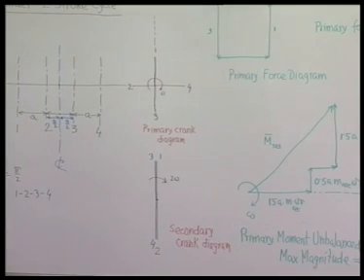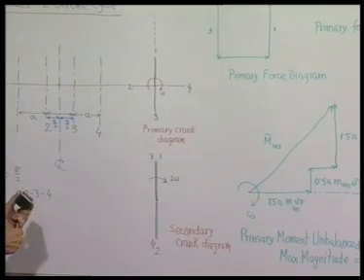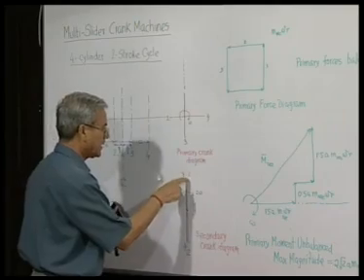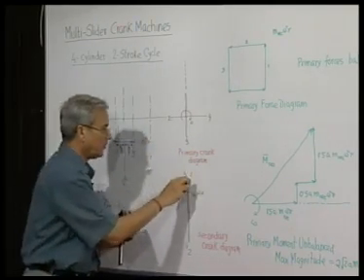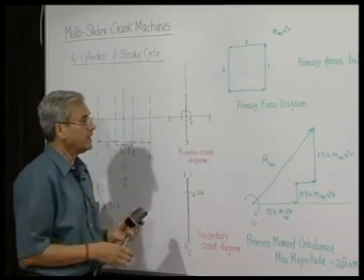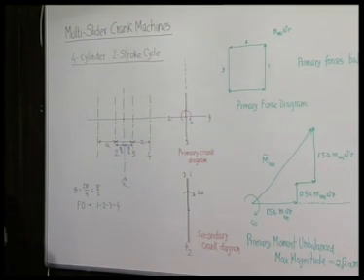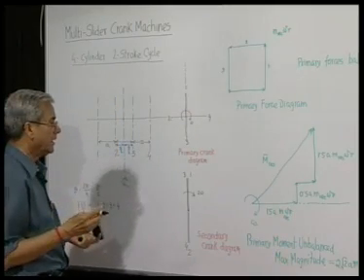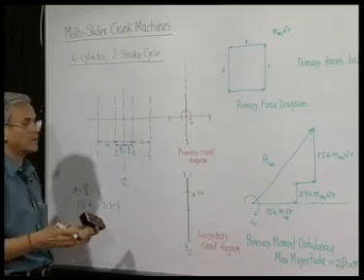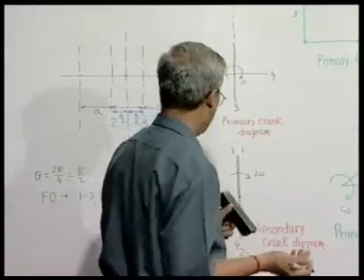So, now to investigate the secondary forces and secondary moments, we proceed in the same way. First, let us consider that we have placed a mass lambda m reciprocating by 4 at the tip of each secondary crank, and then the centrifugal forces produced, we consider their component along this cylinder center line. But before doing that, if we find that those centrifugal forces are balanced among themselves, then obviously their components are also balanced, or 0.